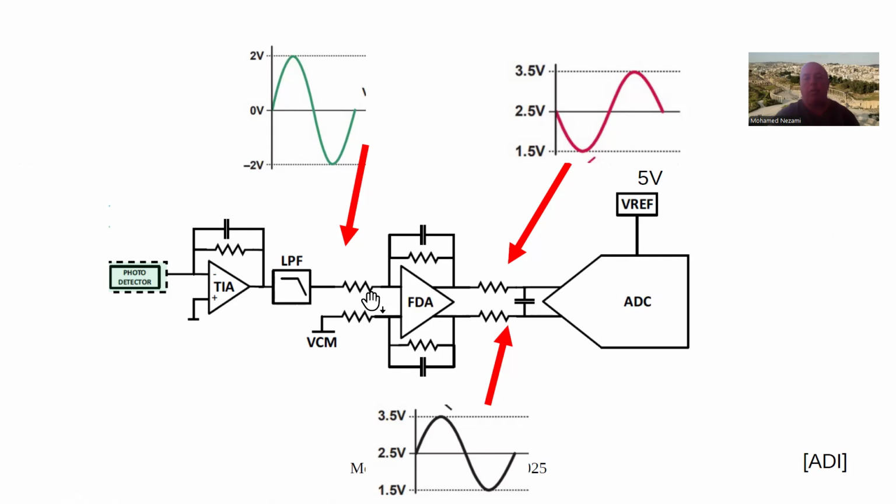A differential amplifier is nothing but really 0 and 180-degree signals at the input and at the output. The beauty of that is that any interference comes in common to these components, whether it's leakage from the power supply or it's radiated. It gets canceled once it goes into the A to D because the lower branch is always 180 degrees out of the other one. We're driving them out of phase on the input, so when we go to the output, the desired signal doubles while the undesired signal cancels, assuming we have a reasonable common mode rejection ratio.